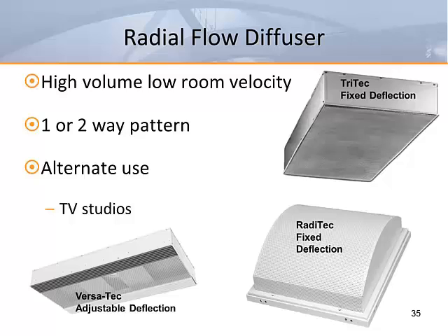The Versatech design discharges air in the center face through an optional perforated, non-adjustable, center vertical discharge, or adjustable vanes in the center, while the outside vanes are adjustable to produce either a tight horizontal ceiling discharge pattern or a deeper hemispherical air pattern. The Radiatech is a fixed hemispherical air pattern, optional one or two-way, with a face extending below the ceiling surface. The Radiatech is also available with an optional room-accessible HEPA filter.